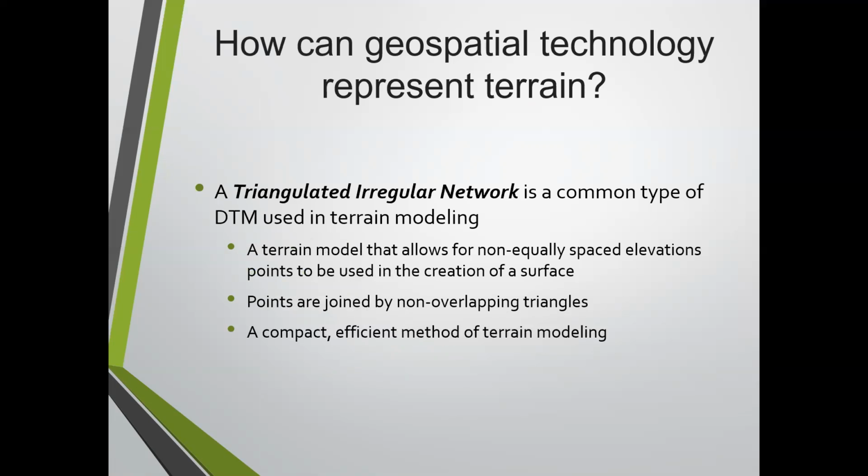This is a very compact method. It's very efficient. And I feel personally, I've used it so long that it's very accurate if you know what you're doing with it. But one of the big things to creating a proper TIN is what we call break lines. Does everybody know what we're talking about by break lines, or fault lines as they are also referred to?